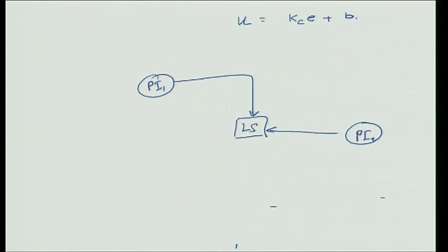These are the two outputs, and this is basically going to a valve. Okay. In the block diagram that I just drew, the reset action B is taken from the implemented controller output U, B is equal to a lag times U, that is what I was doing. Shinsky calls this external reset.